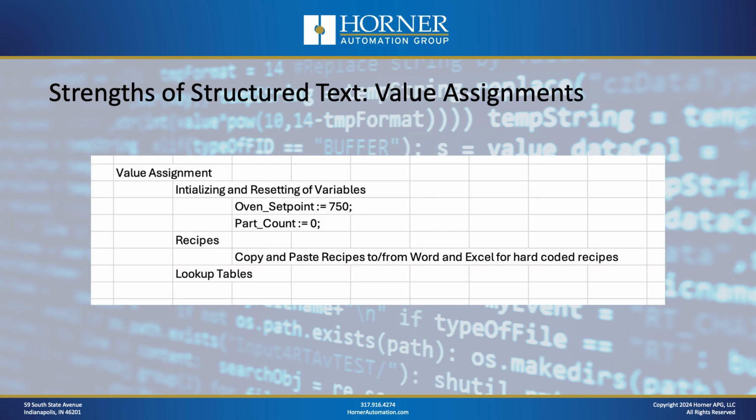For sure. Okay, this is an area I definitely agree with John, and that is value assignments in structured text are really, really easy. Quite often on startup, you need to initialize a bunch of variables, or when you're, let's say, switching from auto to manual mode, you need to turn a lot of things off or reset them to 0. And it's one move block after another in ladder logic. And structured text is just variable := 0, another variable := whatever value you want to assign to it.